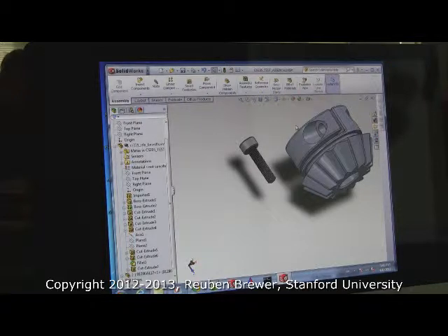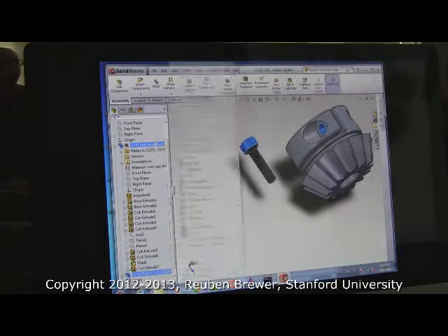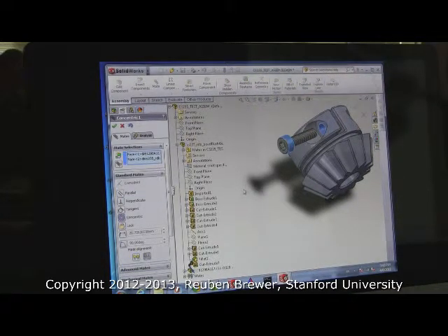Okay, everybody got a screw with no annoying little sketches in it? I want you to select this surface, the screw head, and select this whole surface here with the control key. See how both surfaces are blue? That means I've selected them. Hit the paper clip button. Alternatively, you could do SolidWorks, Insert, Mate. See how it moves the screw to be coincident or concentric?